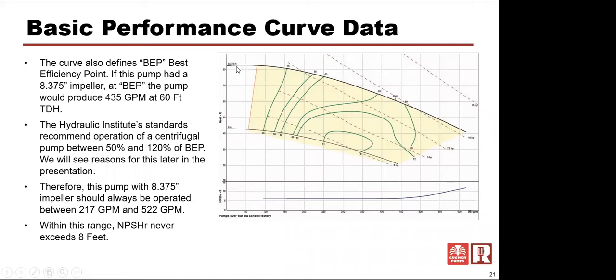And in fact, when you get over here in deadhead, which is what we call that, where you've created so much restriction that there's little or no flow, things really become erratic. We have a curve oftentimes out here, but the predictability of that curve in this area is just about zero. It's just not sure what's going to happen in this area.